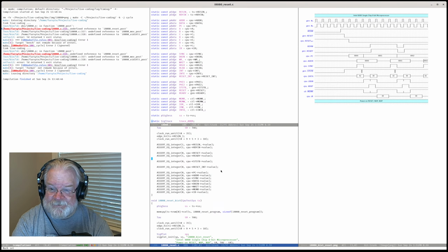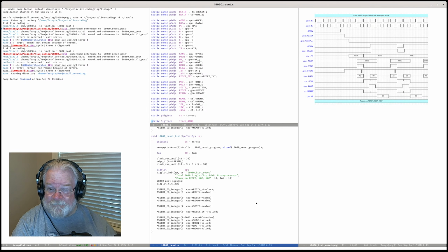Yeah. We need to make sure we start asserting sync properly. We are not going to assert anything about the data bus. We are, however, going to assert that dbin has gone low by now, and that wait has gone low, and that memr has been relaxed. We're not going to assert anything about IR. And we need to do these during BIST as well. And I'm going to do those assertions after we finalize our plot so we can get the plotted results of a failed test.